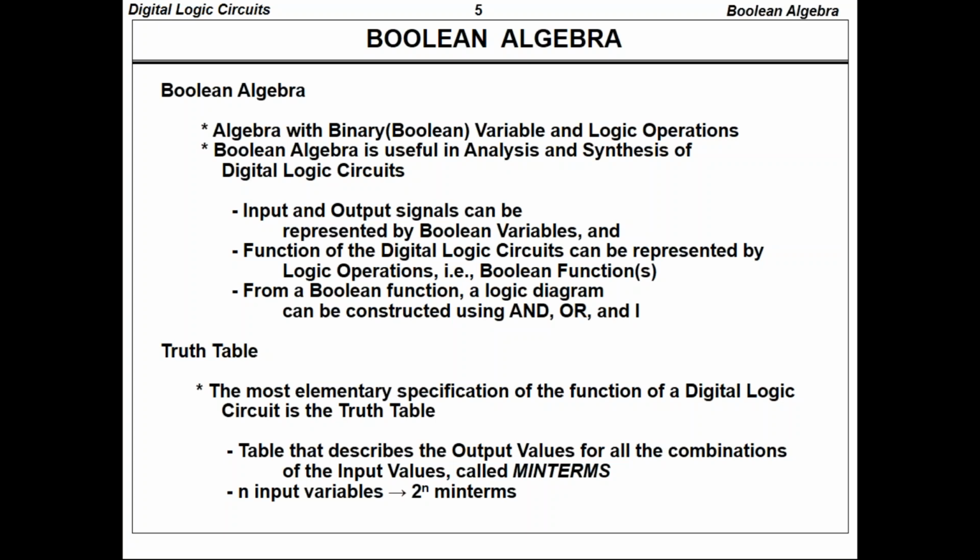If I want to generate a truth table, then from that I will form the equation. For that expression, we are using Boolean algebra, which has a set of rules. It is able to reduce the terms, which means we are simplifying the expression. If I am able to simplify the expression, then alternatively we are reducing the number of logic gates, which is minimization. That's why we consider Boolean algebra to reduce the number of logic gates.